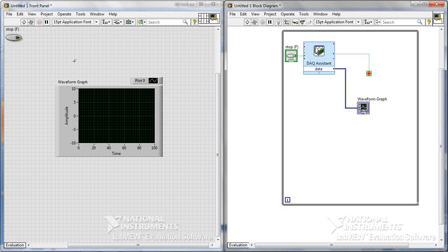Whenever you try to acquire some signals, you have two different sets of connection. One is single-ended, one is differential. Single-ended is nothing but whenever you want to acquire a signal with respect to ground. Now I have given a single-ended. What is differential-ended? Differential-ended is when you want to have positive voltage as well as negative voltage. With respect to positive and negative, you get a differential.